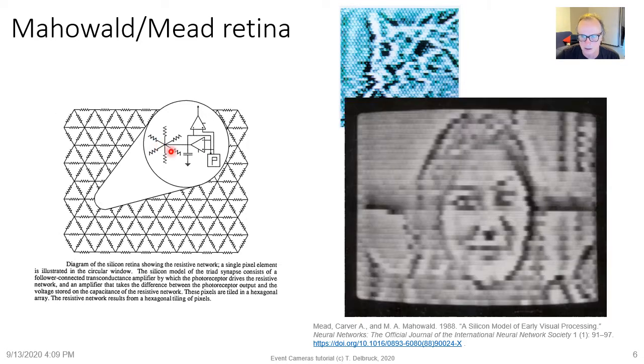You can see that in an output where Misha shot a picture of herself. This is a Polaroid photo made from the multi-sync monitor screen. Misha was just slowly moving her head back and forth here. And you can see now that wherever the intensity is uniform, it goes to a uniform gray level. That's because any place the intensity is uniform, the average value computed by the resistive network takes on the same value as the photoreceptor, and there's no difference, and then there's no net output current.